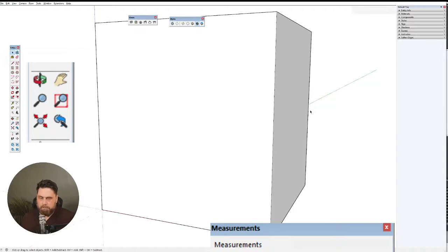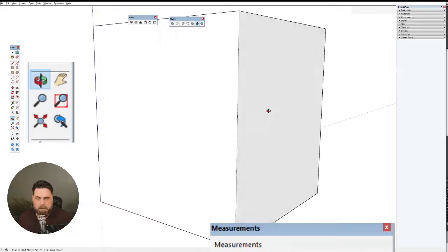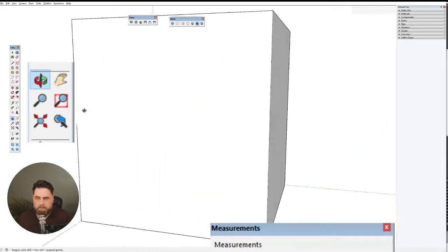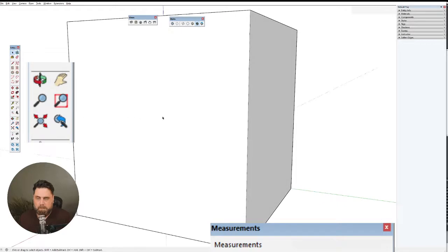And what I want you to do is come to this edge of the box, put your middle mouse button down, and that's going to bring up the rotate orbit symbol, and then just drag to the left to about there, then let go. Now come back to this point. So imagine what you're doing is you're essentially grabbing the viewport and you're rotating it, and you're grabbing it from a spot and you're turning it around. So imagine the window was like a diorama.